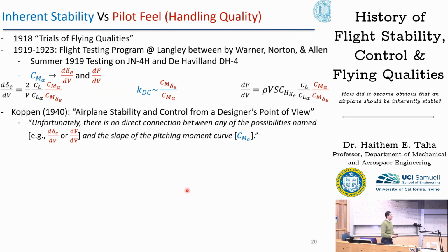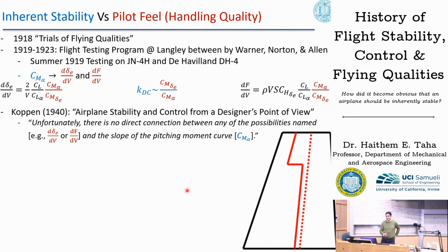So he is referring to the following. Let's consider a tail unit, whether it's horizontal tail or vertical tail. The dotted line is the hinge line, okay? The solid red line separates the movable part from the non-movable part, okay? The movable part that is ahead of the hinge line, this is the dashed area here, this is what we call horn. This is what you have seen in the last problem of the last homework, which is due tomorrow.